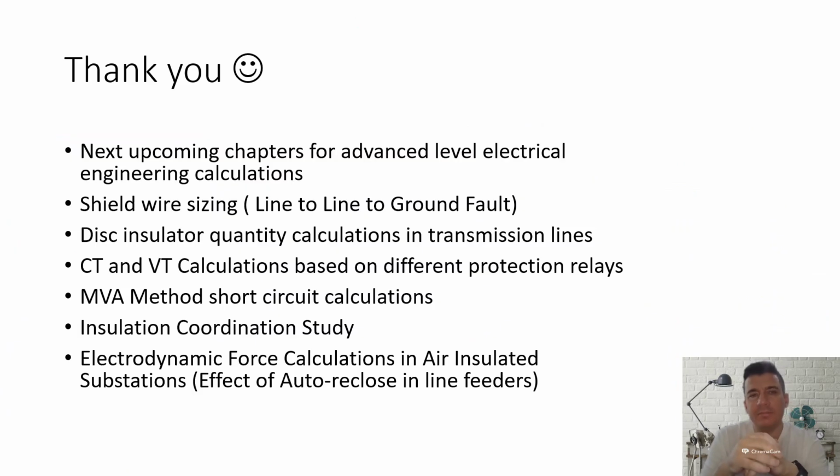Actually, if I have time in the following weeks or months, I will try to put here additional videos and additional sizing tools, Excel tools. Some of them are like shield wire sizing, especially starting from the power plant side. This is very critical, and you need to consider the line to ground fault, not even the three-phase fault. Depending on the connection of the ground of these power transformers, you will see such a fault level will give you a much greater required thickness for this shield wire.